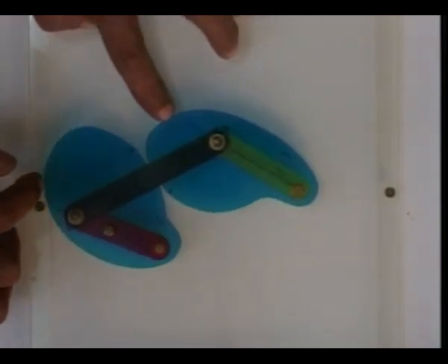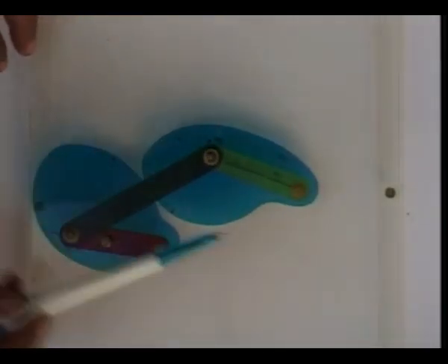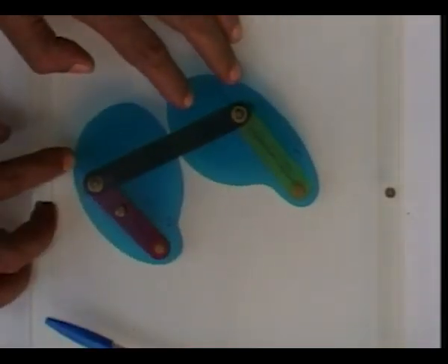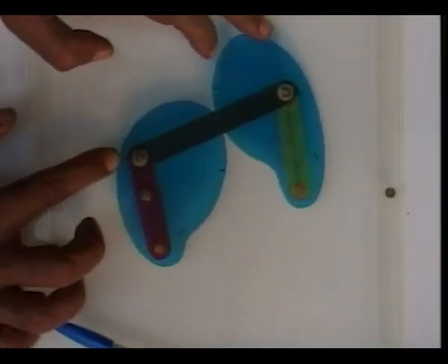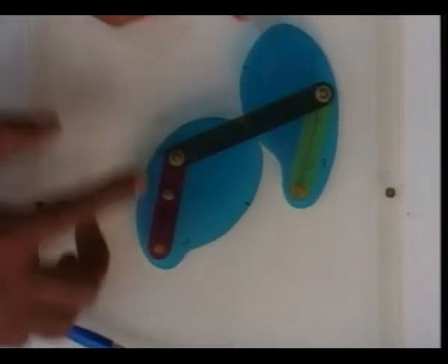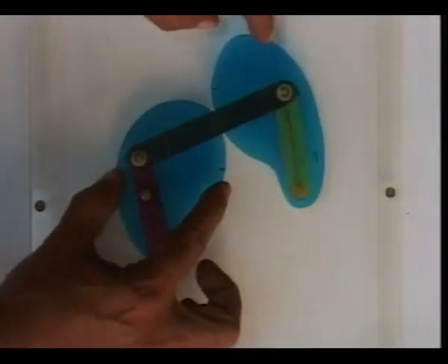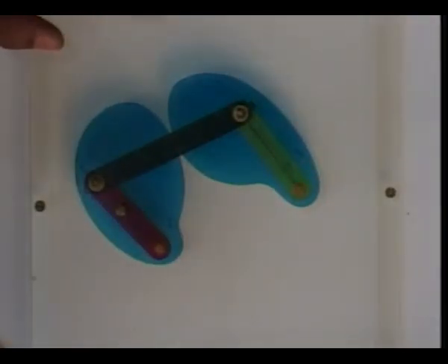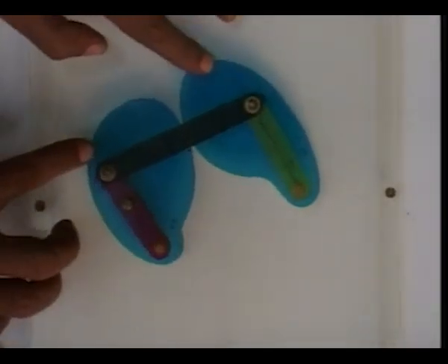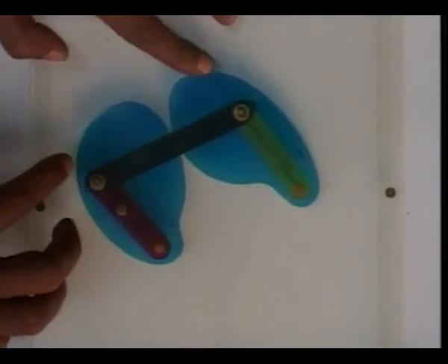But when there is a lot of movement, these two lines separate out. This blue line and this red line are not the same anymore. But around this point, it is only here that these two lines separate out, because the centers of curvature are very different from what they were at this configuration. So this is what we mean by an instantaneously equivalent lower pair linkage.